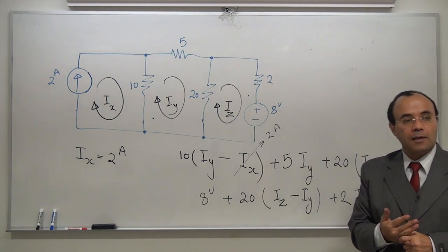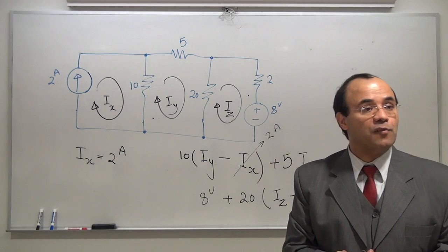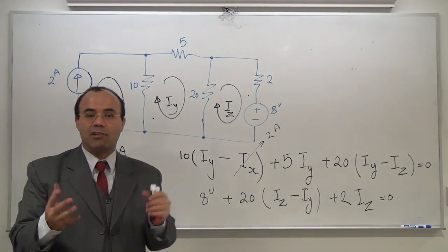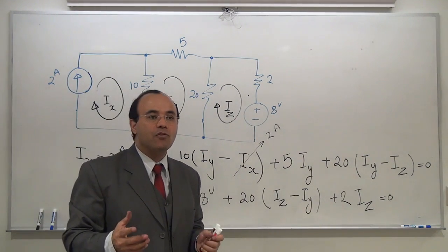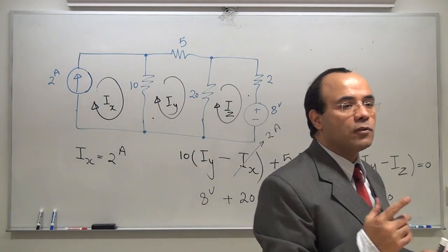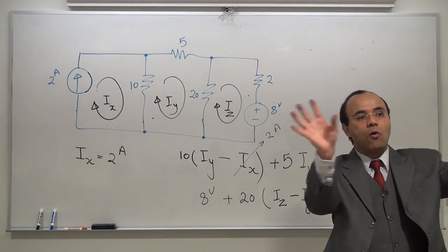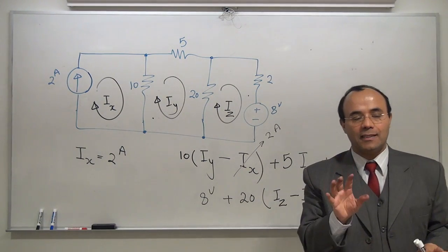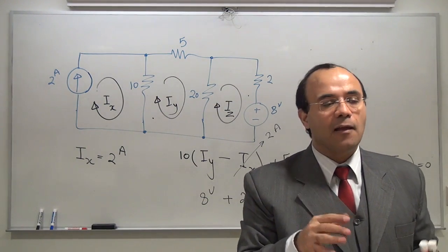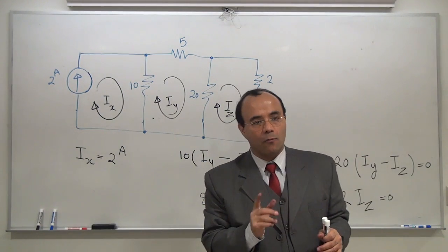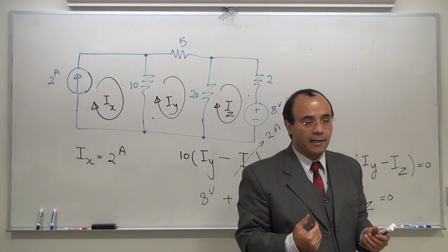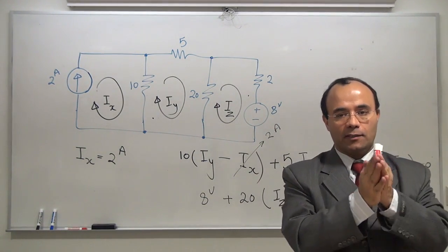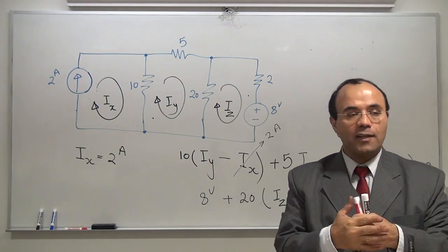What did we do so far? We said that as a result of a different perspective on the equations we got from chapter 2, we can rearrange the equations and collapse the system into mesh equations only. In order to write the mesh equations, we ignore all the polarities and confusing directions of the currents. We only safely and soundly assign the currents to the loops. For my sake, please assign clockwise, because it's a lot easier for us to do grading. Clockwise, and then if the currents are coming into the component in the same direction, you add them. If they are opposing, you subtract them.